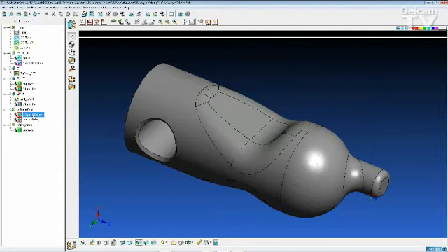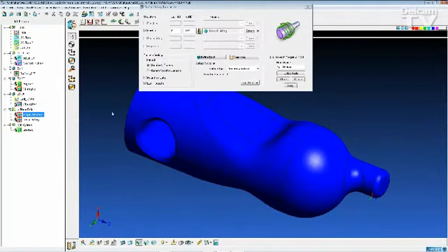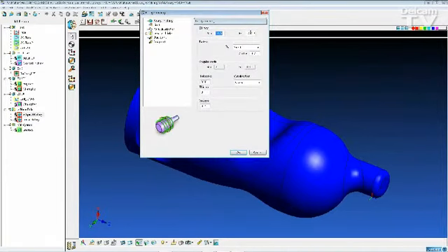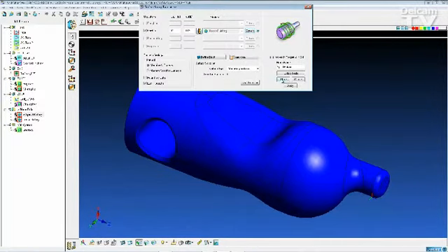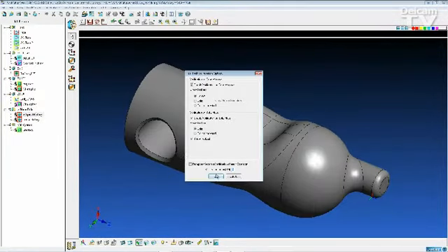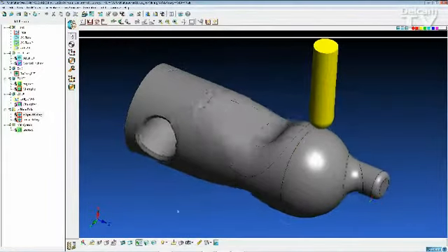Here we have a spiral rotary strategy, which will cut rotationally around the part, and we can set options of how to machine this. So here I'm going to use spiral, and I'm also going to adjust the Y offset so that the tool's machining off-center, giving me good surface footage at the tool tip. So here we go ahead and take a look at the toolpath.